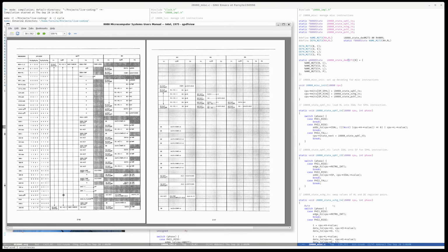So here's DAD. M1T4 is a do nothing but deliver control to us in M2T1. M2T1, we have R low goes into accumulator temp. During M2, we get the L register. We can't have 2 different registers moving across that data bus. Remember, we've got a single 8-bit data bus out of the register bank.